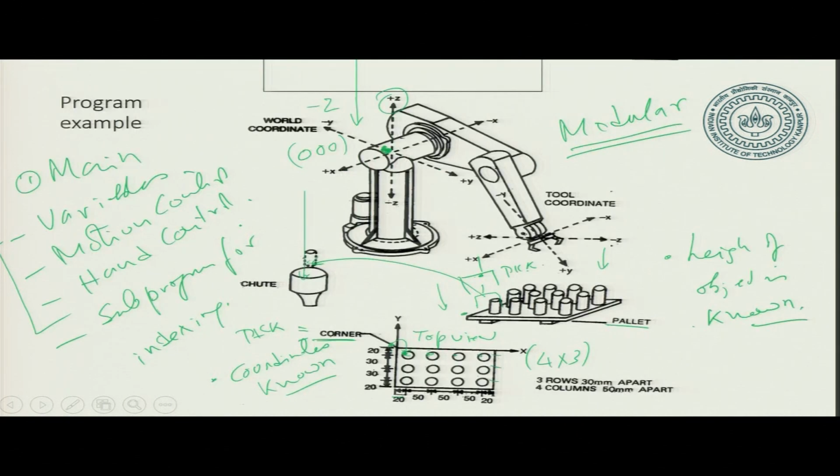So, we go here and see after it has caught, again it goes this way to where it was. So, as I had explained, when we catch an object and we lift an object, then essentially we are moving down in straight lines along this z axis always. So, when we catch, we essentially go down like this. After catching, we lift also like this, okay. That is essentially for safety.